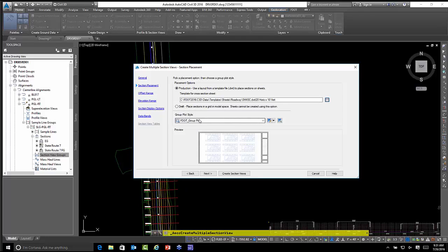And then we have a group plot style. What the group plot style does is that it tells our cross-sections the distance to space themselves from one another in an X and Y direction. Okay, I've gotten calls before saying that it'd be nice if in this group plot style we had a grid that was turned on that would aid us in labeling our cross-sections.